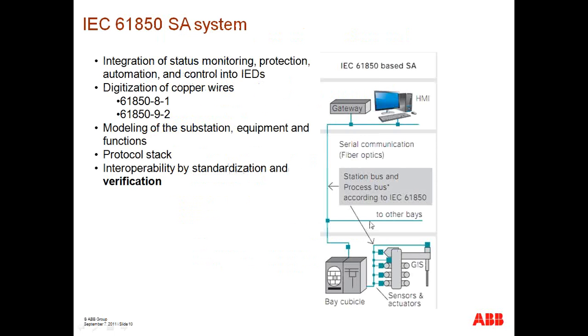Okay, so when we talk about the station bus, the station bus includes two components. It includes the exchange of information between IEDs. So if one relay, let's take for example a breaker fail scheme. A breaker fail scheme involves the exchange of information from a device that just operated a protection function and another device that's going to start a timer, for which it will wait, pick a timer, to see whether the fault is clear or not. If the fault is not clear, or the input signal to that particular device is not quenched within a certain amount of time, another sequence of events will be started.